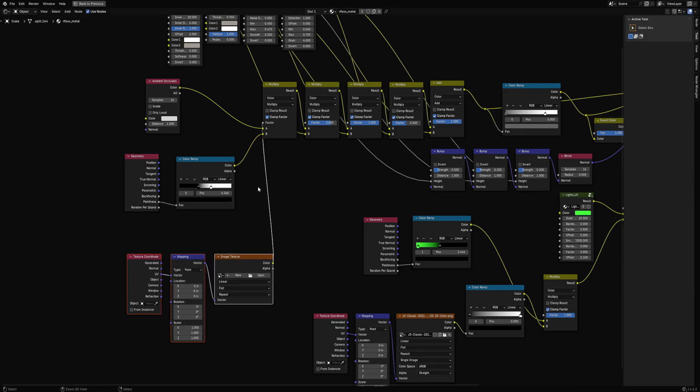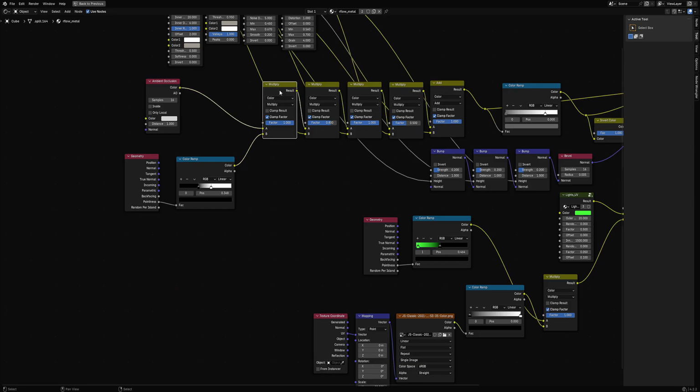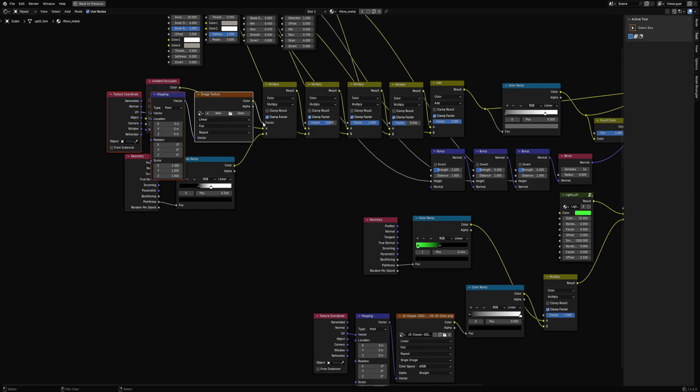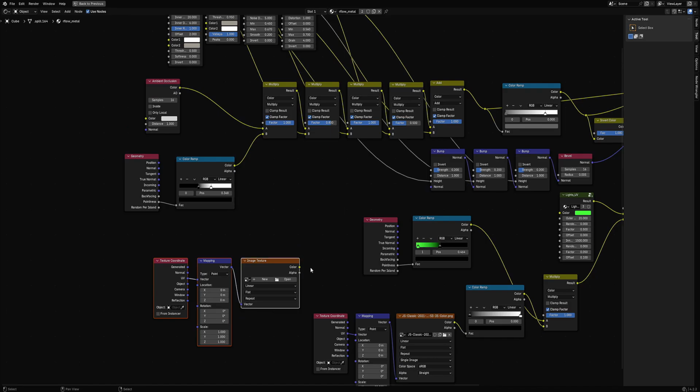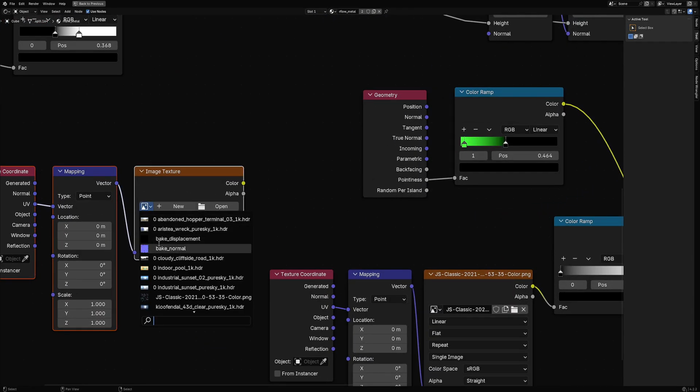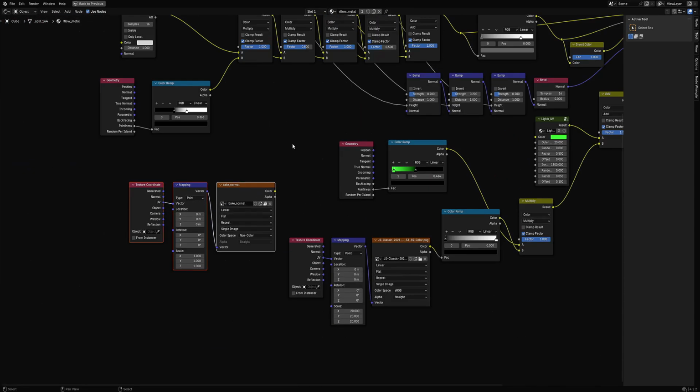So Control T and then just detach. What I did there is just use this node because it has an empty input node. Control T, I just use that to create this combination of nodes, then detach and bake normal.